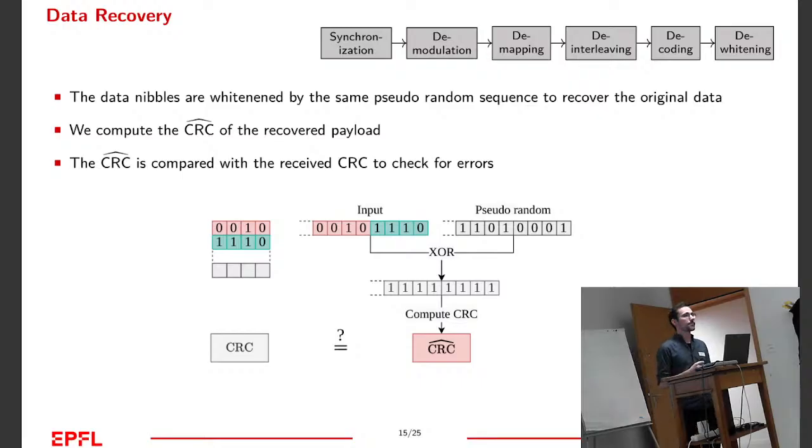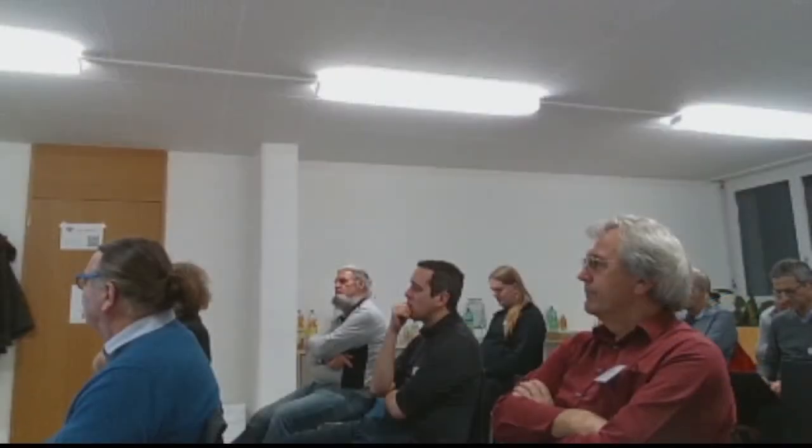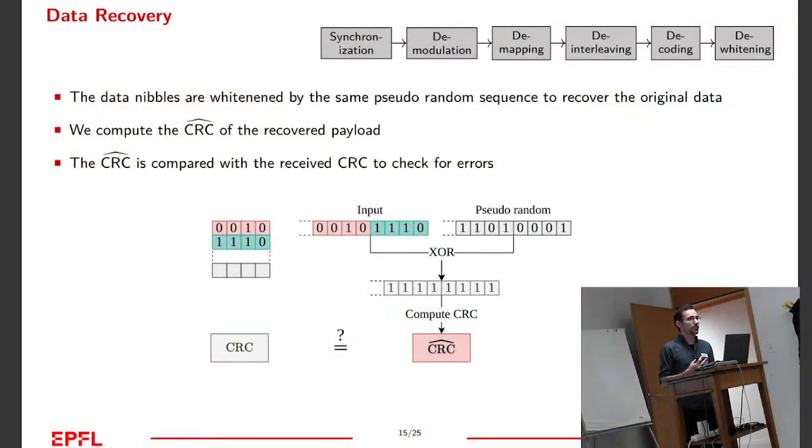And how is it random? It's pseudo-random, so it has the statistical property of being random, but if you generate it here and at another location, you get the same sequence of 1 and 0. But if you look at it, it looks like a random sequence. And the starting value of the seed is? Yeah, I think it's all 1 for LoRa. Oh, they start all ones. Yes. In cellular, there is also some pseudo-random sequence where, for example, the seed will be user dependent. But for LoRa, everyone just uses the same.